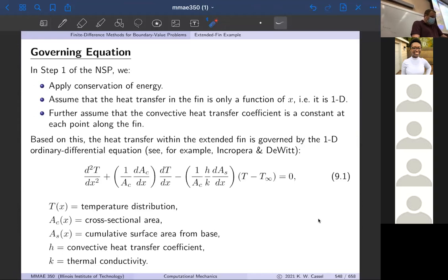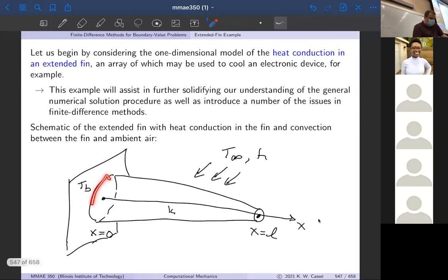And if you look in books, look online, you'll find all kinds of experimental correlations for H in various situations. You won't find one for exactly this geometry. If it's tapered, you will find one for a circular cylinder, which has the same cross-sectional area, but that won't account for the fact that it's stuck on a wall over here.